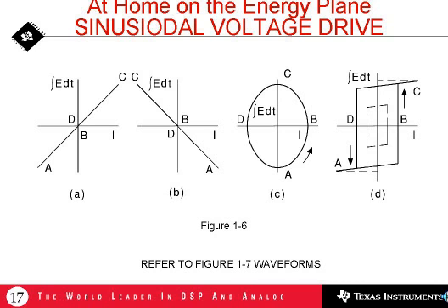Now, the final characteristic shown in D is an idealized inductor made with a metal alloy core. Metallic materials like molypermalloy and so forth have a near ideal characteristic. Notice that the vertical sides of that characteristic are nearly vertical. If they were truly vertical, that would indicate an incremental permeability of infinity.